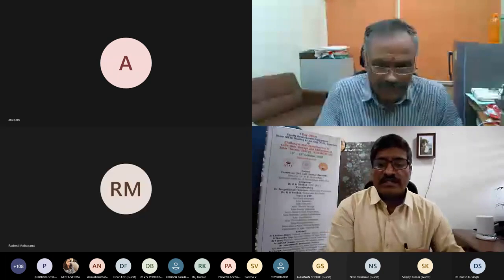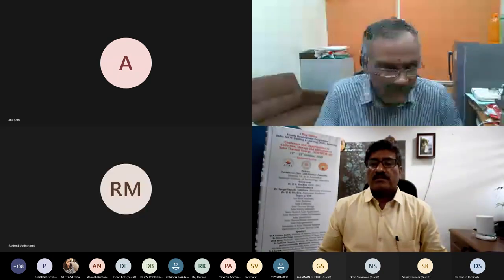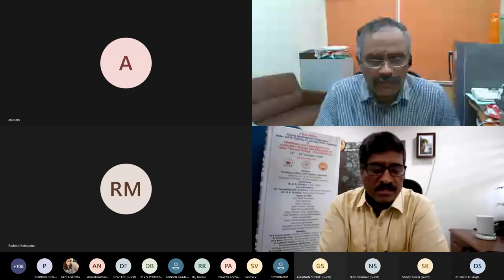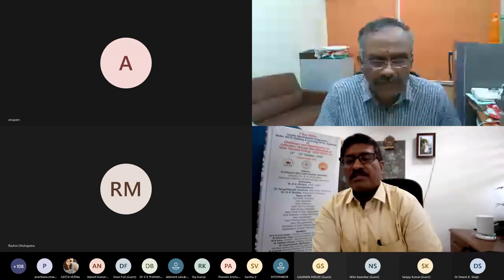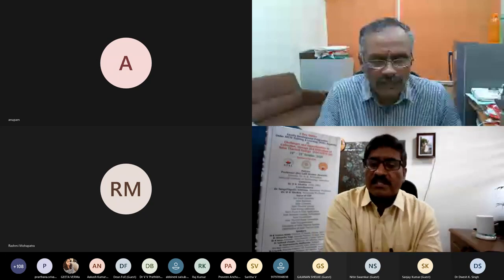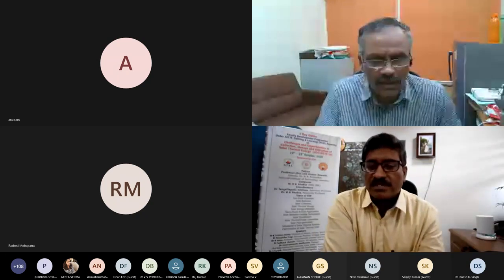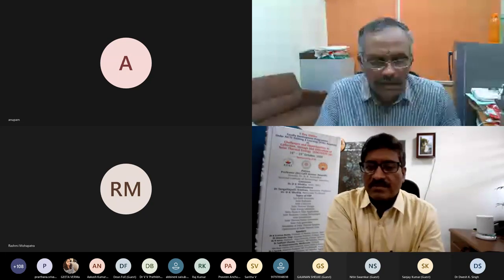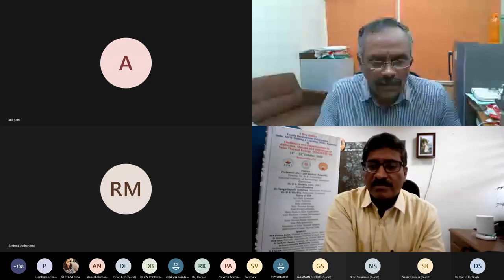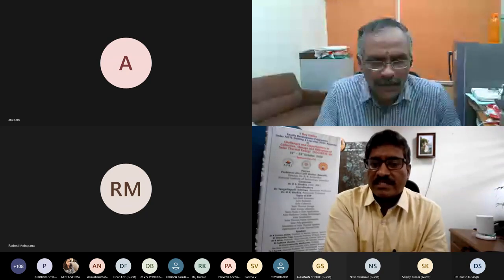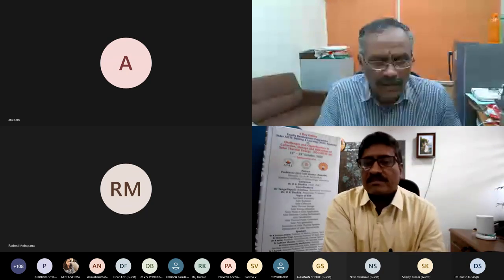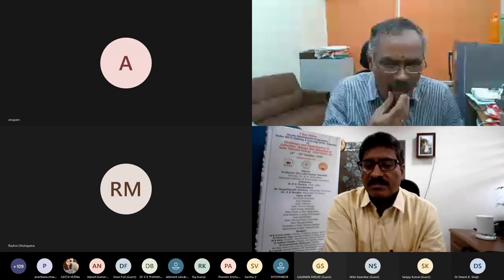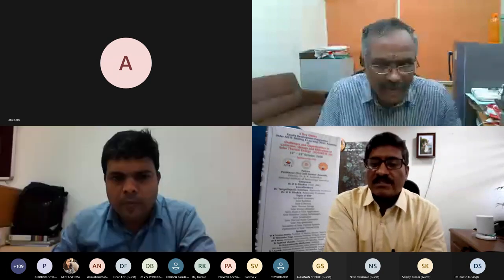Sir, I want to add one point on these cooling towers. Okay, please go ahead. In polygeneration, we have a desalination system. Recently, some industry people approached with a challenge, especially for the evaporation losses from cooling towers. There is a desalination technology, a water cycle, where air can be humidified and then followed by dehumidification, like condensation. Because they already have hot water, if they apply this heating, humidification as well as dehumidification for a cooling tower, they can recover the water.